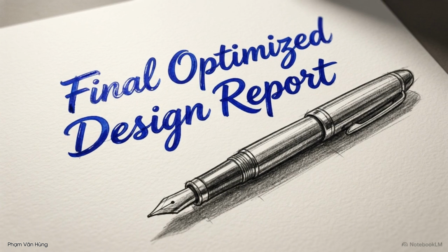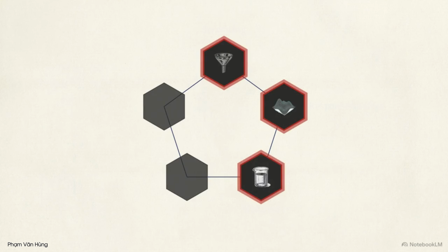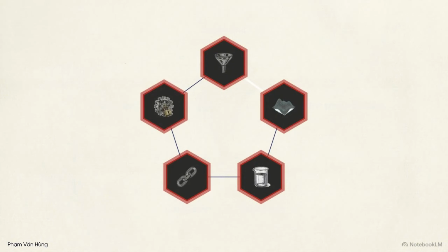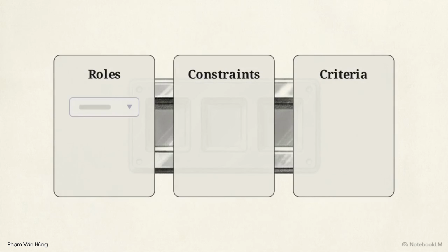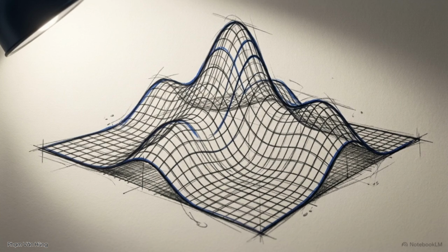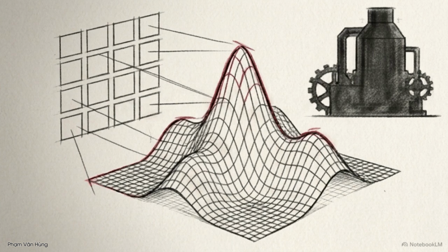Properly mapping your factor change difficulty upfront prevents operational bottlenecks on the floor and guarantees accurate statistical readings in your final report. We have moved from isolating variables in screening to modeling boundaries in response surface, blending mixtures, accounting for covariates, and respecting physical limits with split plots. Across all these methods, the rule remains the same. Correctly defining your factor roles, constraints, and optimality criteria gives the software exactly what it needs to generate a highly optimized model. Open the sample datasets in JMP, set your parameters, and start translating your unique operational